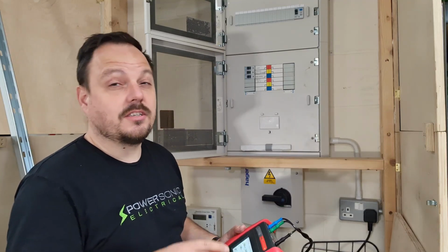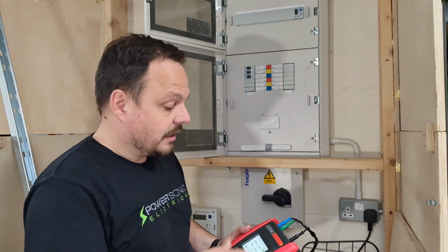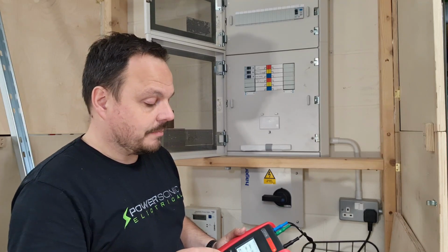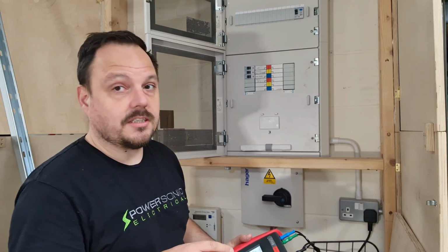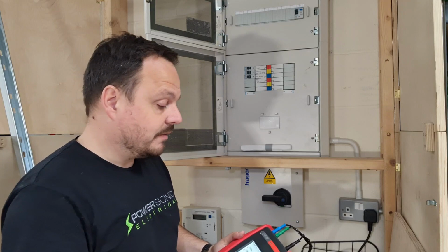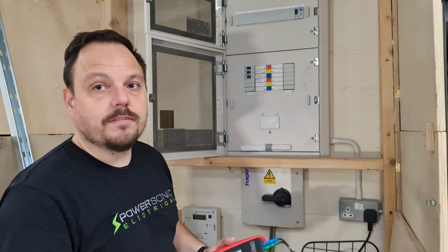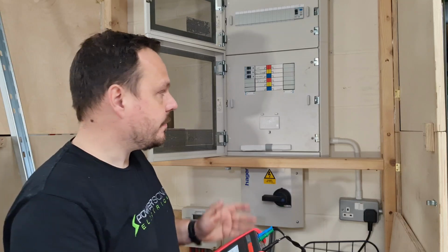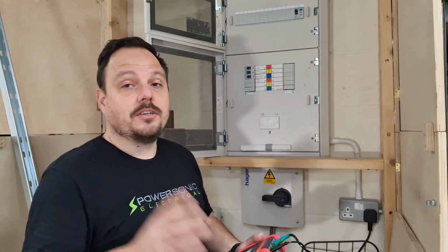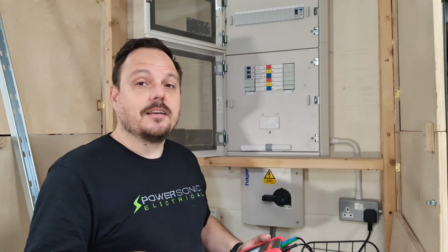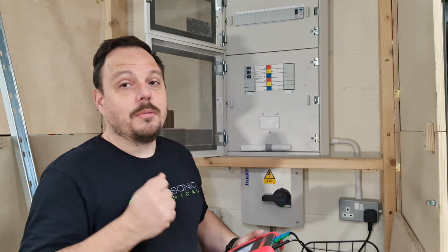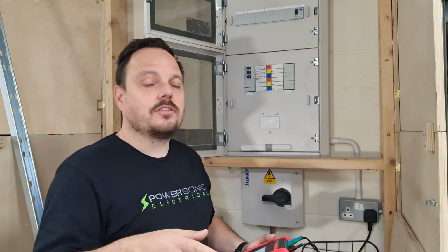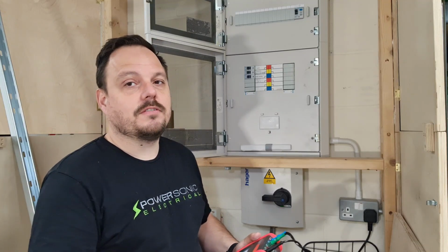So when you carry out this test, it gives you that information, which is good, and also that we've got just over a kiloamp of PSC. So we've got that on there as well, and we've got near enough 0.4 kiloamps on the line to earth PFC. I'll jump around the ring now. I'll go and get those values for the other sockets. I'll make a note of the highest value, and then we'll have a look at how all of this pulls together by using calculation, test results, and some of the reasons that we might have seen some differences in both those things.